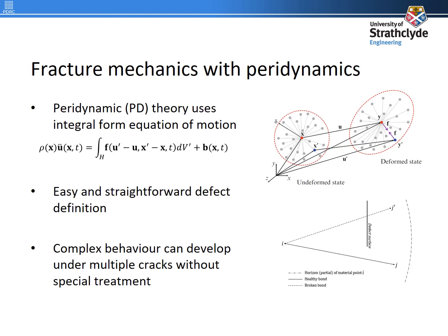Now, I would like to briefly talk about the peridynamic theory. Peridynamics is a non-local continuum formulation introduced by Dr. Silling. Unlike classical continuum mechanics, the equation of motion in peridynamics does not contain spatial derivatives. Instead, the integral form equation of motion is applied everywhere, regardless of discontinuities.